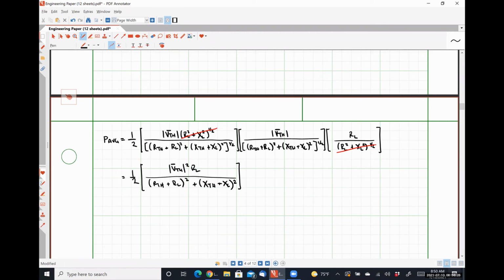It absolutely, right? So the reactance is the X terms there. So if XTH plus XL, yeah, it's in the denominator, right? So it doesn't matter whether that combination is positive or negative. If it is non-zero, our average power is being reduced by definition. So we can use that to our advantage, okay?